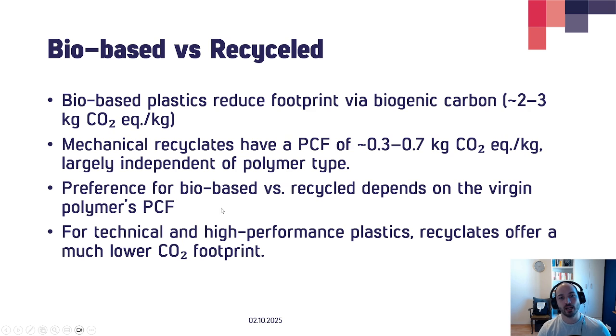Then the preference for bio-based versus recycling plastic depends on the virgin polymer's product carbon footprint. The higher your footprint, the better it is to recycle. And the lower the footprint is, the better it is to make it bio-based. For technical and high performance plastics, recycled plastics offer a much lower CO2 footprint than the bio-based ones.